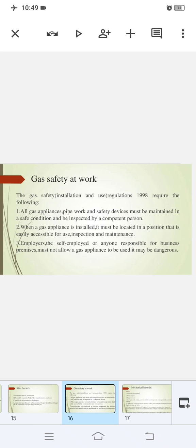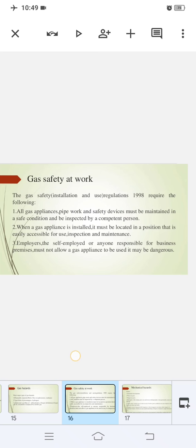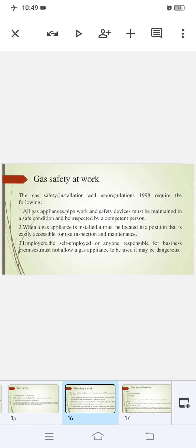The cyclone separator consists of a short vertical cylindrical vessel with a conical bottom, and the upper part of the vessel is fitted with a tangential inlet. The outlet is at the base, and the air outlet is provided at the center of the top portion, extended inwardly into the separator.